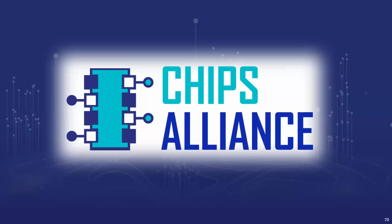Really, it's on a single die. We have been able to put chiplets on all 4 sides of the die. So there's really no limit on how many chiplets and edges that you can use. Now, really, the limit is you start connecting multiple chiplets up in a pipeline or spanning them out in 2 dimensions. It's going to be your packaging technology.